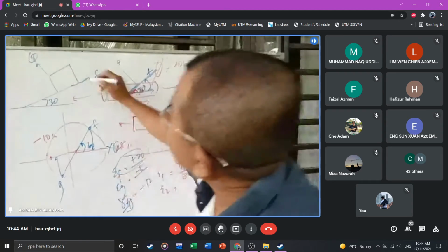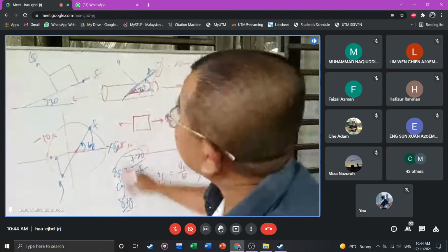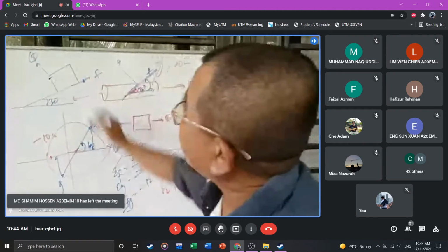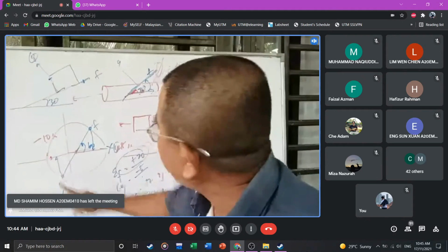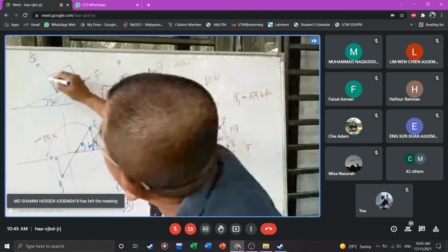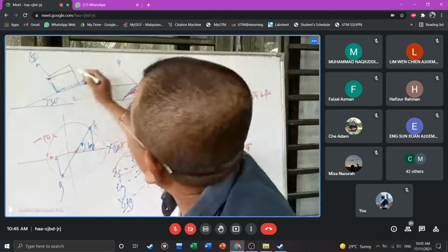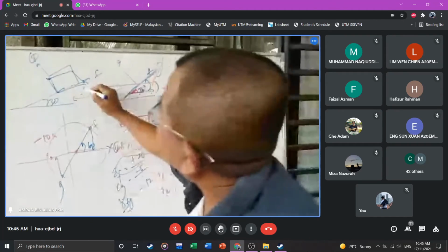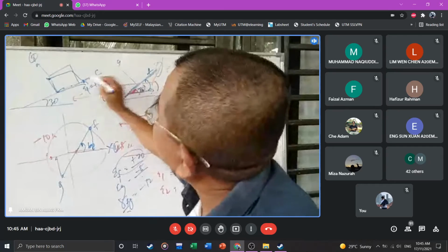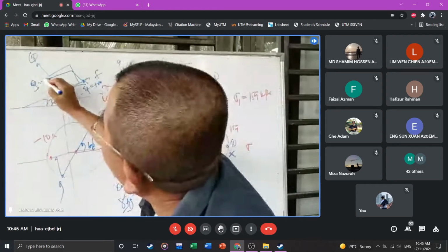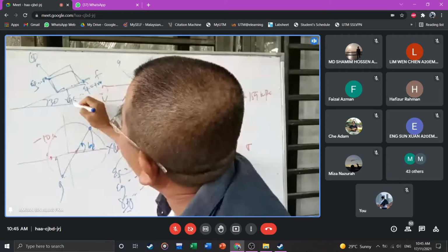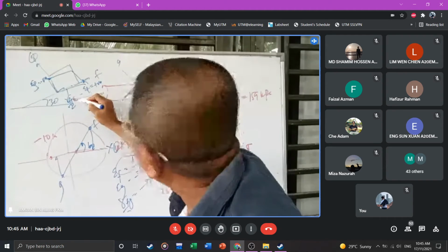In F direction, positive. In G direction, negative. And then the angle here, you read the G1, negative, bigger. So that is the element. So epsilon F there is positive, epsilon G there is negative, and then gamma FG over 2 there is negative 12.